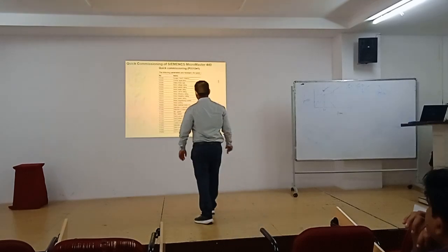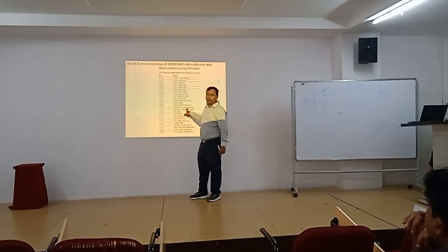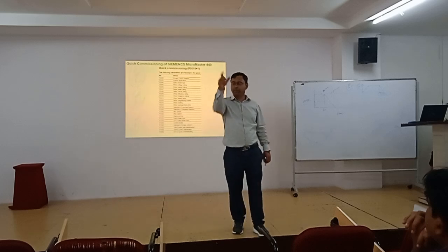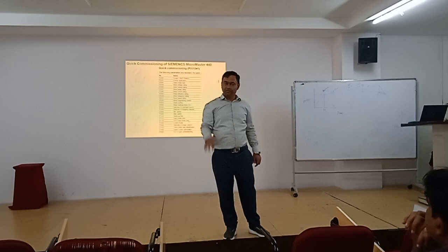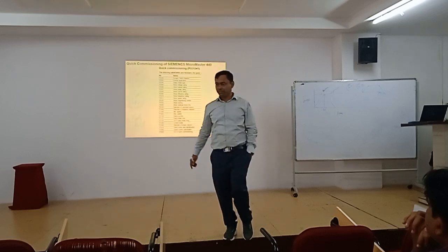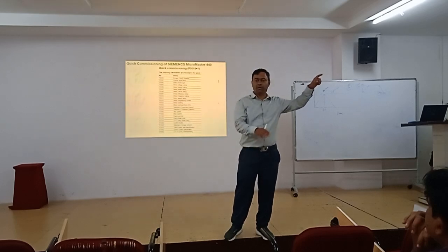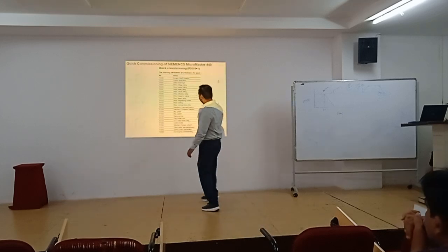Correct? Then you can see 700, selection of command source. From where do you want to start your motor? You can start it from the input/output terminals, or from the operator panel given on the drive. Normally we always go for the terminal, because it will be connected to the PLC most of the time. You switch something on SCADA, it gives a command to the PLC, and the PLC operates the VFD. So it will be through the input.